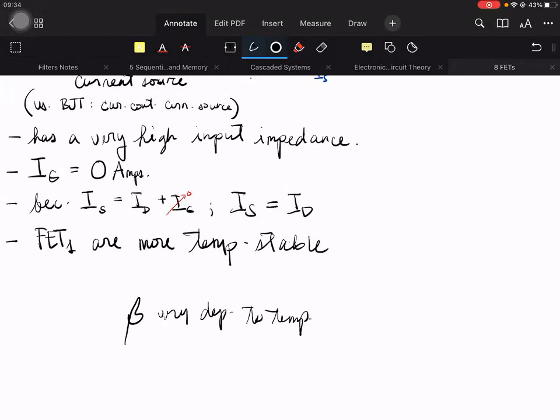But we've decided that the voltage divider bias is a more stable circuit, such that if we use a BJT that has a fluctuating beta due to temperature, okay lang, no? At least the voltage divider could manage fluctuating values of beta.